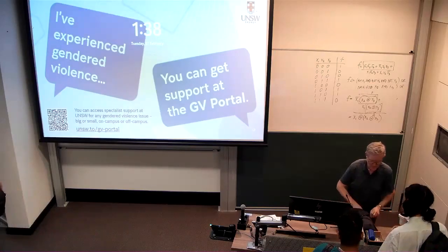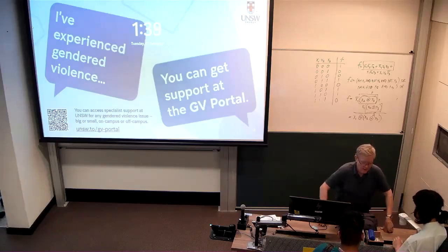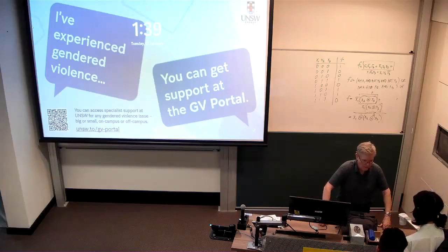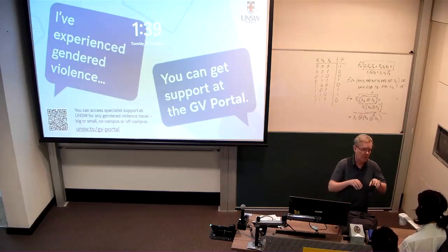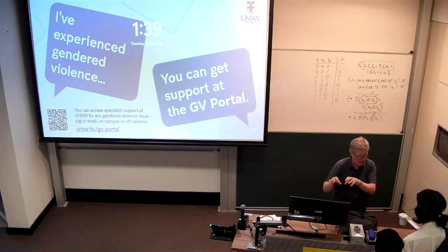I'm not too sure, and I don't want to confuse you, but essentially we'll talk quite a bit about state when we come to so-called finite state machines, which are a structure that we use for sequencing operations. That's how you control which bits are going to happen when, because with a finite state machine, you assert control signals that determine which pieces of hardware, which components, get activated in each clock cycle.